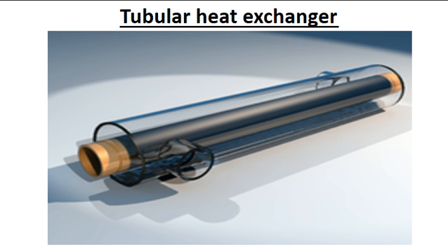Double pipe heat exchangers are the simplest exchangers used in industries. Here you can see a tubular heat exchanger where there is one tube within another tube. The structure at the top is known as the shell and the one within the shell is known as the tube. On one hand, these heat exchangers are cheap for both design and maintenance, making them a good choice for small industries. On the other hand, their low efficiency coupled with high space occupied in large scale has led modern industries to use more efficient heat exchangers.